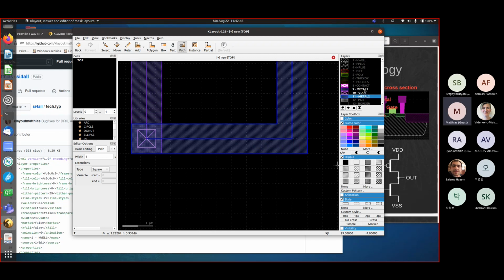Yeah. And now you see there are names now. So these layers have names. These layer names are not saved into GDS. So if you save a GDS and someone else loads it, don't expect these layer names to be there, because GDS only has numbers. But this other person you give the GDS to could also load this layer property file. And then again, he will see the layer names and know what each layer means.